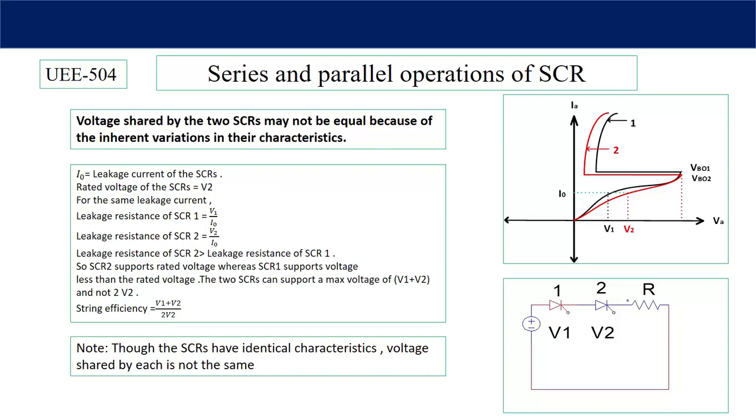So the leakage resistance of SCR number 2 is more than that of SCR number 1. So SCR number 2 will share more voltage than SCR number 1.